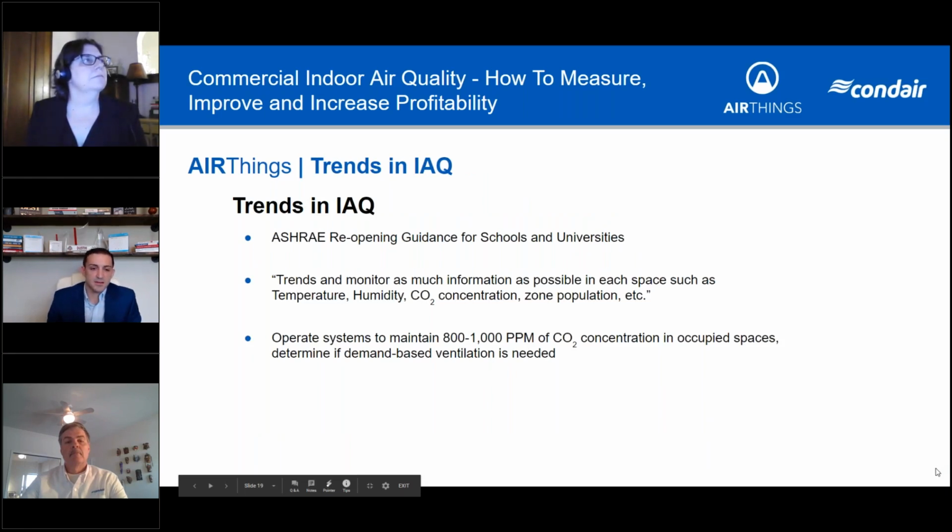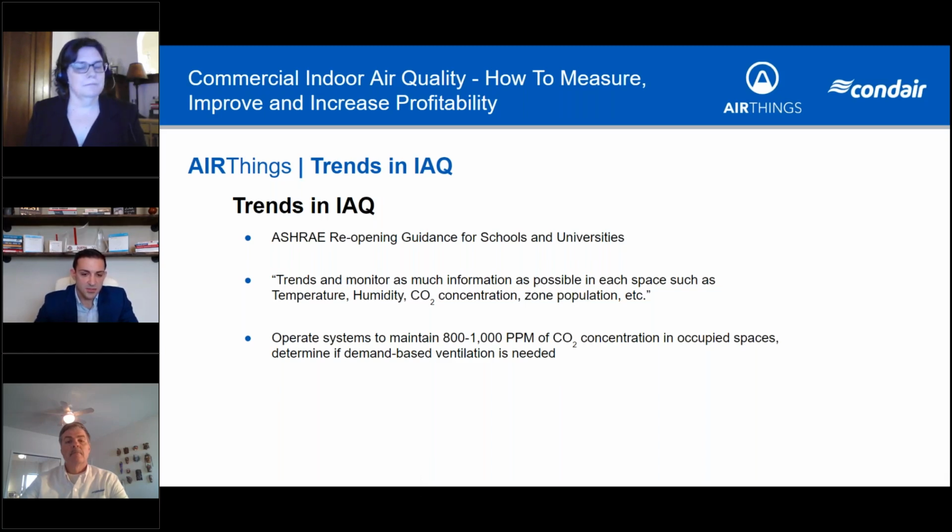All right, so I've hit on a few of these too, but just to touch more on base trends in IAQ, I did mention ASHRAE, and specifically they just released a reopening guidance for schools and universities, and this is a direct quote. So trend and monitor as much information as possible in each space, such as temperature, humidity, CO2 concentration, zone population, et cetera.